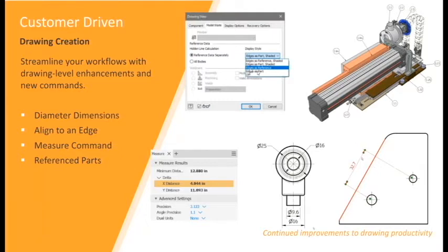And then again, in the top view there, that is your referenced components. So display style, this is what's added now. You can have your reference components be displayed in a number of different ways. As mentioned, edges as referenced, shaded, so that's new. Edges as a part, shaded. Edges as a reference was normal to 2020 and older. Edges as a part, all that means is the edges would not be dashed. They'll look like a normal component, like the other shaded components, and so on.